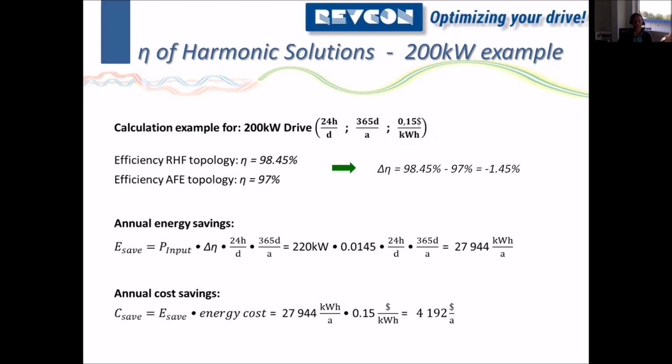with a newer fancy design, whatever. And the active front end would also have a lifetime of maybe 8 to 9 years. So you would have to replace the drives, but you could still leave the passive filter on. Maybe you could do some tests to make sure that it will last for another 8 years, but the design is made for 15 to 20 years. It's passive components, so it will last for a very long time.